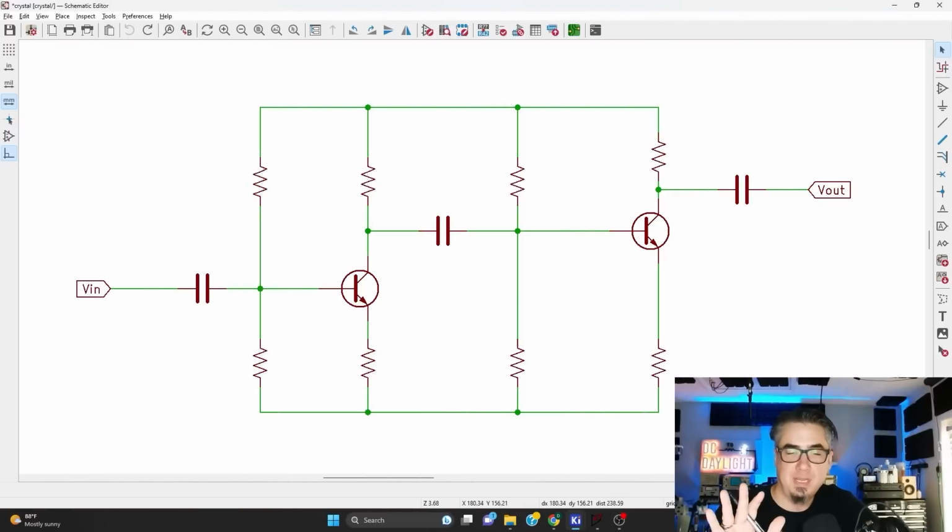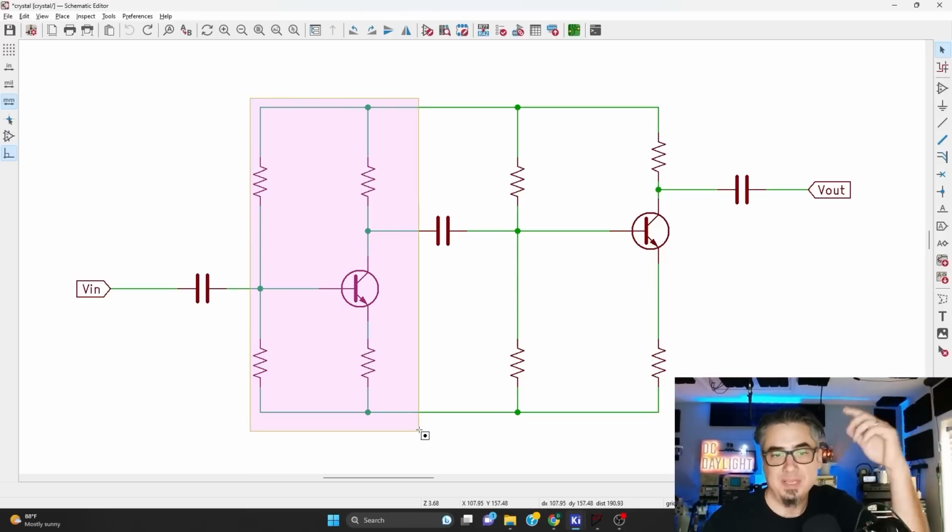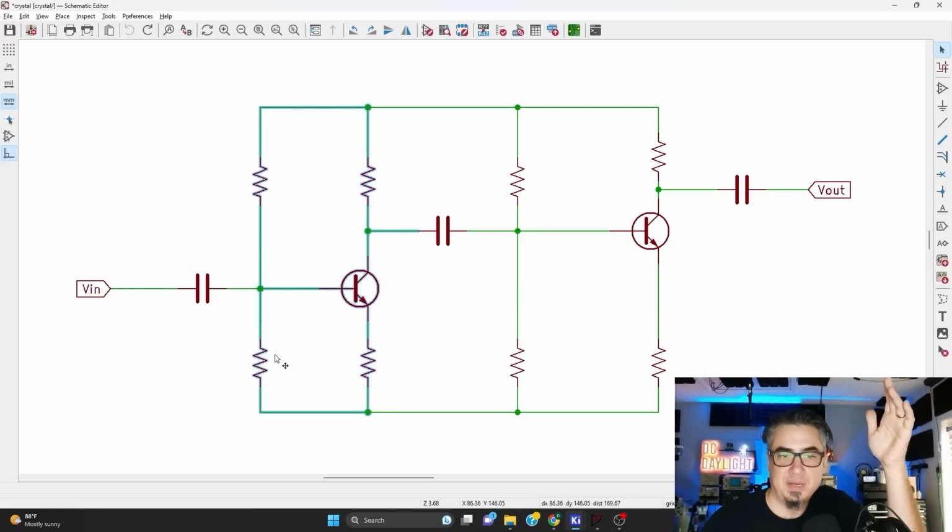So the next application we're going to look at is using capacitors as AC coupling, or we could call them DC blocking capacitors, right? Because that's exactly what's happening. So when we set up a transistor amplifier, we basically have, in this case, a voltage divider bias. It's a common emitter amplifier because the emitter is going to ground, and we have this collector resistor up here as our load. Now that will feed the next successive stage of the next amplifier.